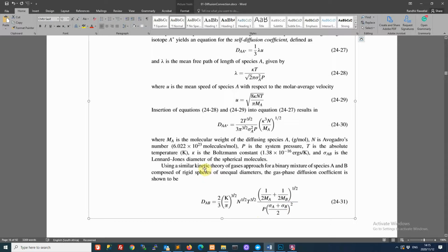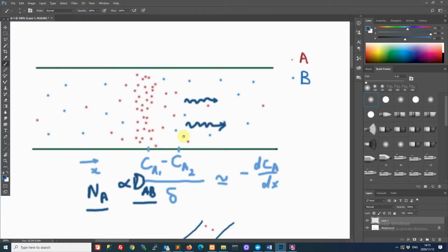So that's what's available to us now, and we don't have to go through the painful process of trying to measure the diffusivity. Of course, that's always an option to us. We can always construct an experiment like this where we apply some concentration difference and then measure the change in concentration over time, and then back estimate what the molar flux must have been, and so fit a diffusivity through it. So that's how these things are done.